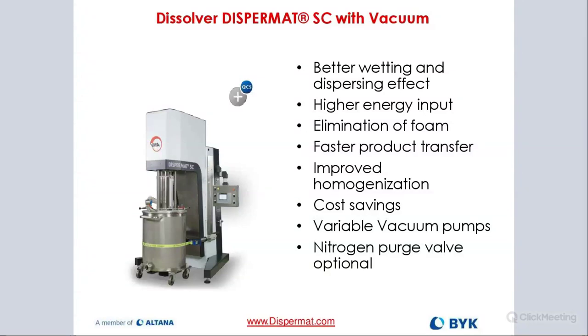So that's kind of like what's happening with the air entrapment, the air bubbles inside of our slurry. So when we remove the air, the media, the beads have much more access to the particles and are able to put in more direct energy. So that is the advantage of removing all the air.